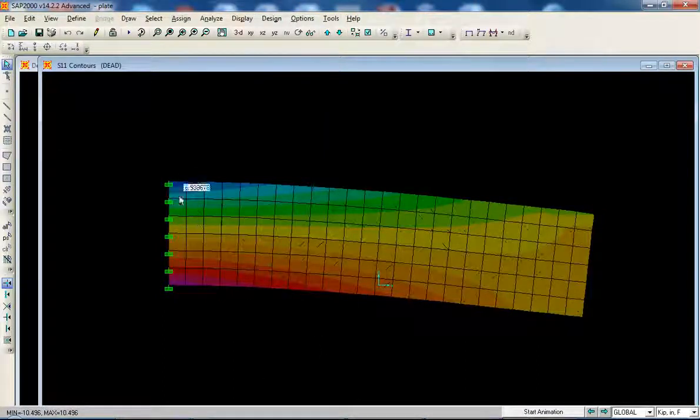So you can see it's 9.10 here, then goes down to 0, and then negative. It's kind of linear, so actually that is true for every single cross section, but because the moment, remember, is triangular, you get the most here. But this is the stress distribution of this beam, and this appears to be the tensile stress, the stress in this direction.